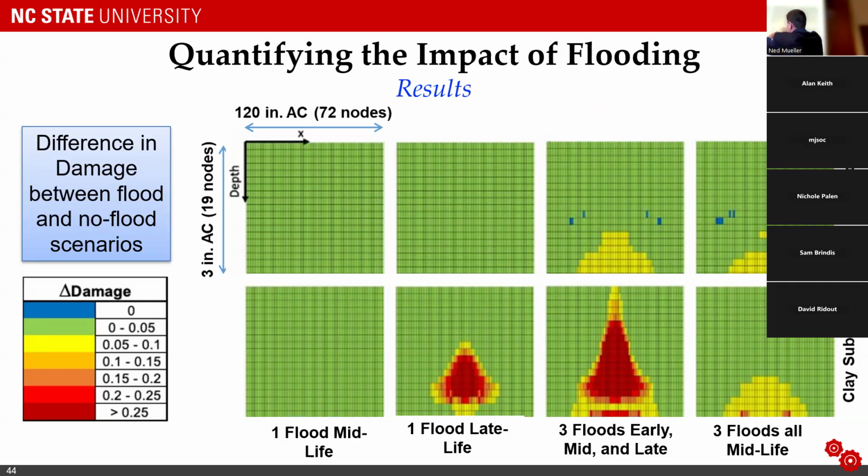And then as it distributes, the reason you see that load, that damage at wider widths is that it's being distributed over the pavement, along the profile of the tire traveling in the X direction. Correct. And the Y is the depth of that asphalt concrete layer. Yeah, so it's kind of coming right out of the page. Apologize that I didn't make that clear.